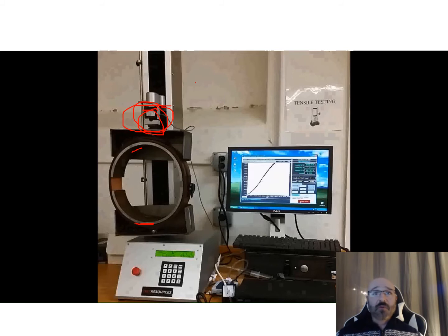I ended up doing this before and went well over 1,200 pounds. I never was actually able to get these straps to break with this machine. This one only goes up to 1,000 pounds, so I had to do some manual testing and move to some bigger machines after that. But under the 1,000-pound tension testing right here, I did not see any failures, so I was well within my safety factor limit, going with that DuPont ST801 glass-filled nylon for my strap. That was really great to see, because you'll even see lifters breaking the cast lever buckles on the traditional lever buckle type of belts. So to see that this was even stronger than some of those was very promising to see in my initial testing.